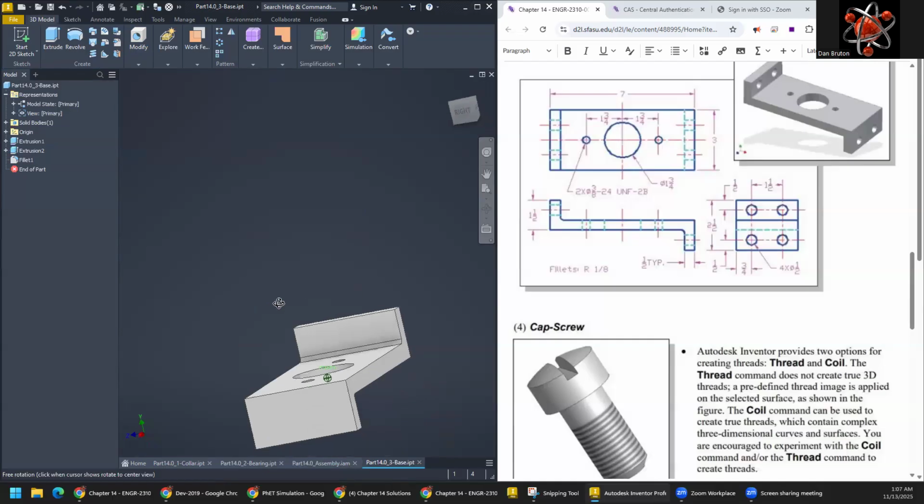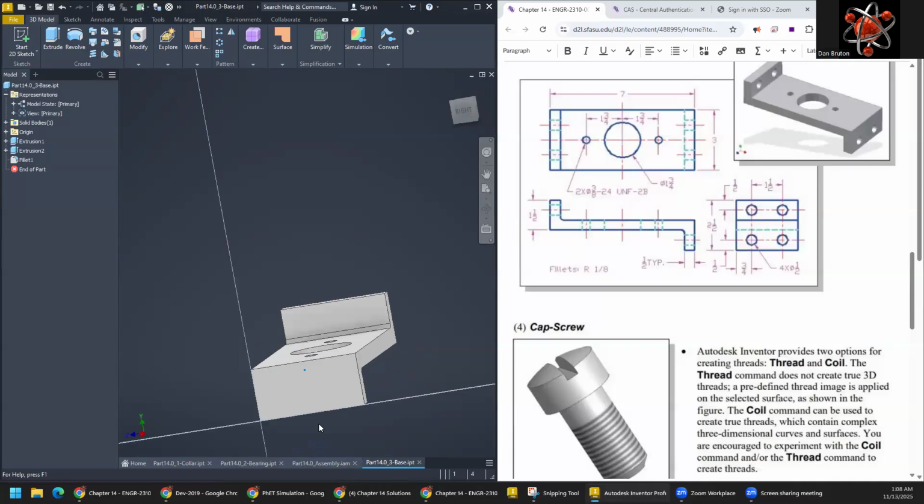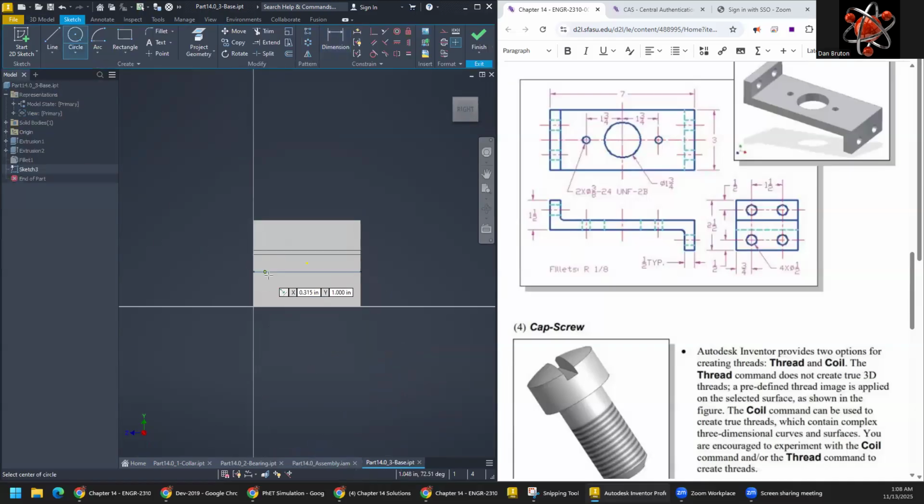Anything else? How about some more of these holes? So we're going to place these holes on this surface and drill them all the way through. We need arbitrarily spaced some holes here, I guess they need to be lined up this way. That would be good. Okay, and then we need to make them properly sized, which would be a 1/2 inch. Just make sure all of those are equal. So right here and then there and there and there and there.